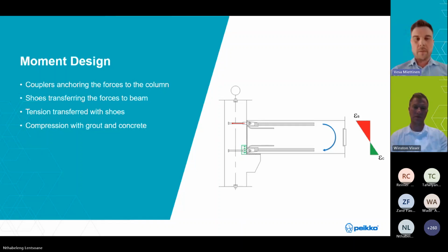In our column connection, we also have a nut typically on the joint, because the joint thickness is thicker and it's easier to place it in the column joint. So there we can also transfer the compression forces with the anchors, but in beam connection, the most common case is that we transfer only tension forces with these items, not the compression force. Of course, the shear, as we will hear later, will also transfer with these connection items.